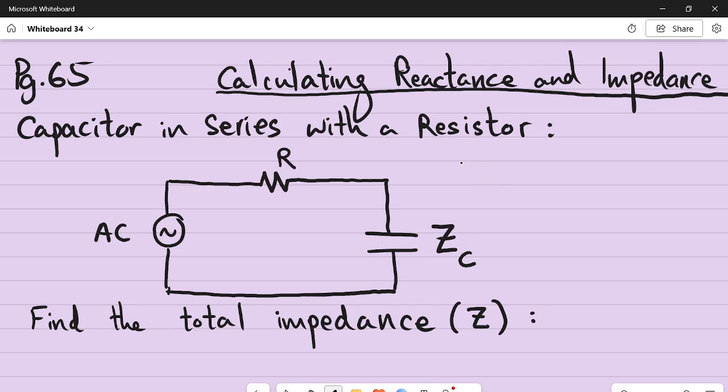So the total impedance is equal to, because it's in series, resistances add, yeah? So that's what we're trying to do for 9 marks, to work out what the total resistance in the whole network. But we call this impedance because we're dealing with an AC source. So it's the same thing. It's going to be measured in ohms.